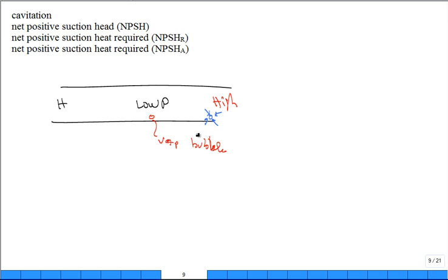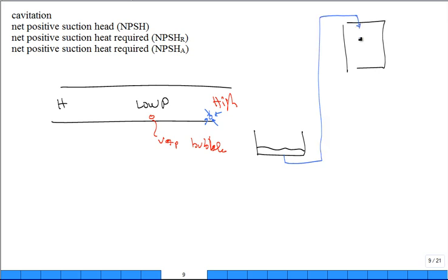So how do you prevent cavitation? Never let fluid go to very low pressure regions. So what you do is you try to keep the fluid always at a high pressure throughout the system. One of the classics is if I wanted to take fluid out of this tank and pump it up into this storage tank right here, I may have mentioned this already, and I wanted to have it routed like a piping network, go like that, right? And then just dump it into the top of that tank and it would fill it up. Where would I put the pump?